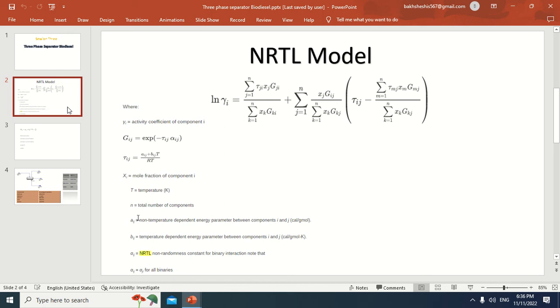NRTL uses the following calculation methods: for liquid, the NRTL method for VLE; Cavett's method for enthalpy and entropy; for vapor, ideal gas, RK, Virial, Peng-Robinson, and SRK methods for enthalpy and entropy, like the Wilson equation.